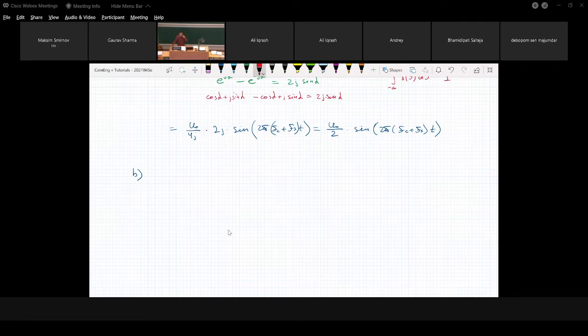Yeah, the question is that we have a negative range for the transfer function of our filter. We have a transfer function with positive sign, but we pass a signal with negative sign, a delta pulse with negative magnitude. It's absolutely fine, because the minus you can just assume as the phase of your signal. This phase equals pi. You cannot distinguish signals by phase with simple linear filters. How do you distinguish them? You distinguish them by frequency.